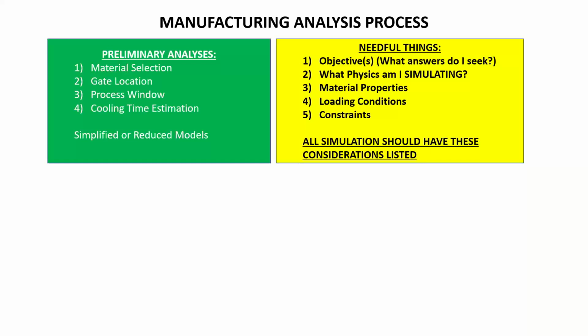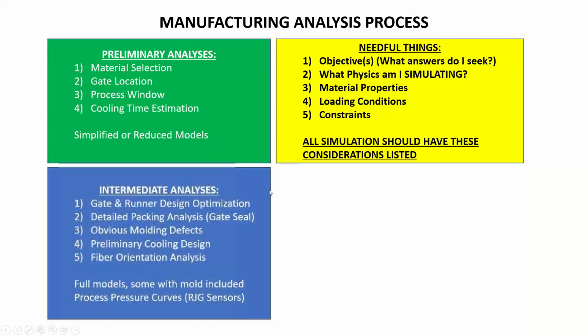And then you look at things like cooling time estimation, looking at, say, the thickest section of a part, and there are hand calcs for that, and there are simplified tools for that. And depending on where you're at, are you estimating, or are you doing something a little bit more involved? Are we getting just a little farther along than merely estimating, or is this a kicked off project? In which case, that's going to guide some of those decisions.